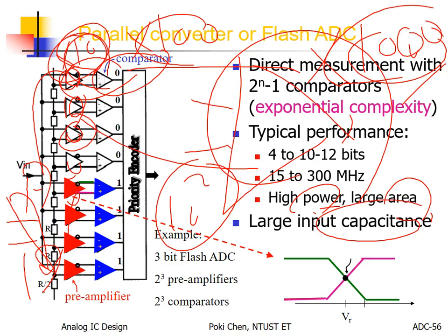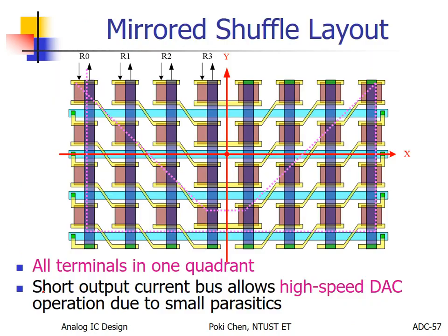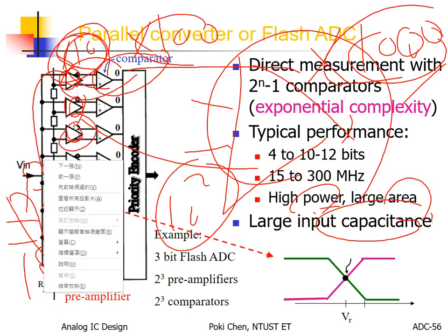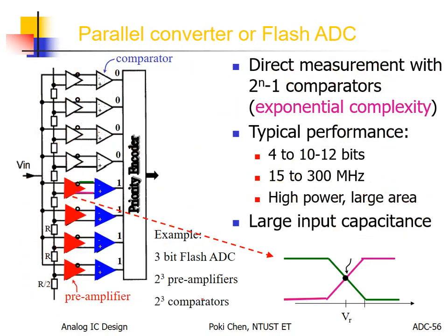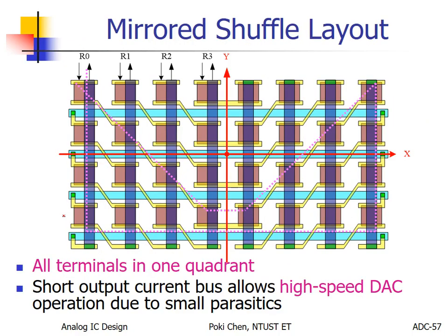That is the second reason. So for that, I have the third reason. From the beginning, I told you I have 2 reasons. No, 3 reasons. But later, okay? Anyway, the other issue to remind you is how to generate good enough quantization levels for all of them. You need to match each resistor to all the others. But how? Allow me to show you this.